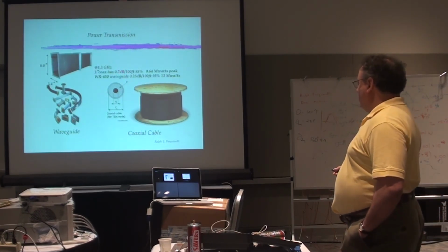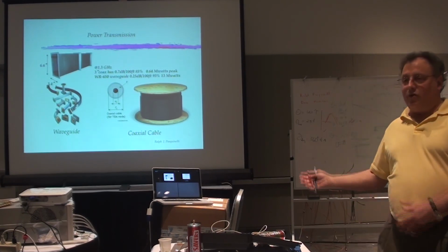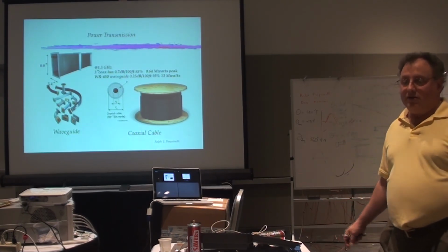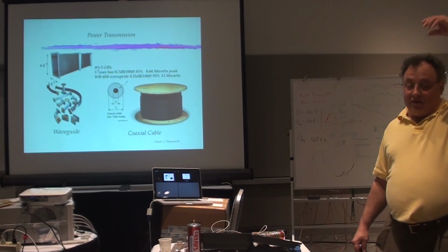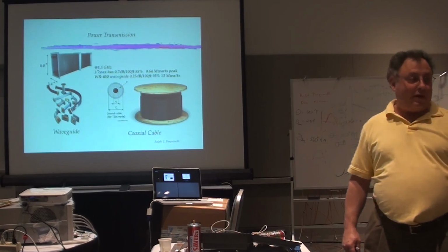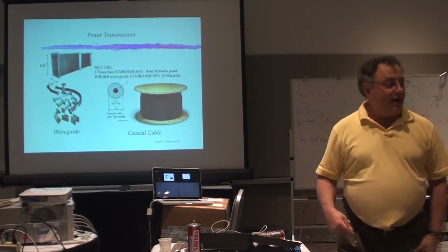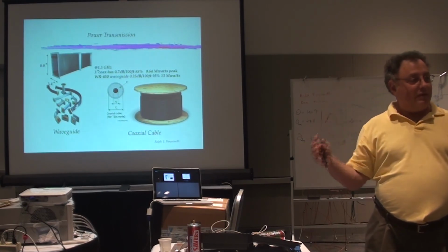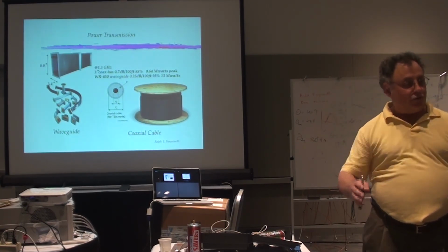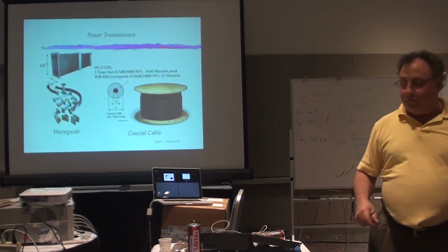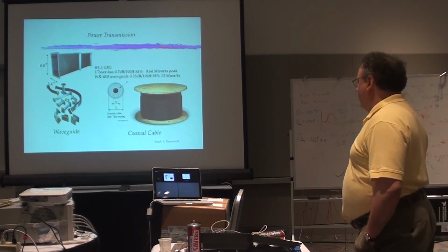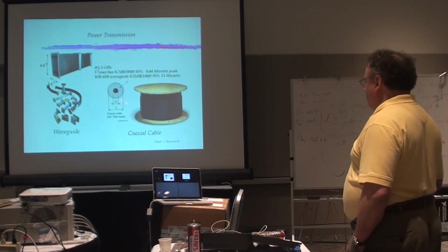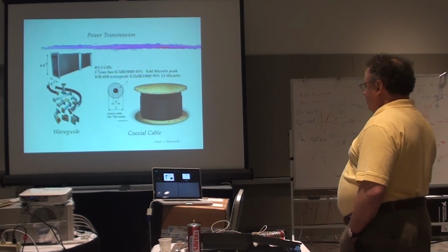Am I going a short distance? Am I going a long distance? Many times you'll see in an installation that you'd like to have the amplifiers upstairs if at all possible, because they are going to break. And it would be nice to fix them up in the gallery by having maybe something you just roll right in, or you fix it in place. Or you have something down in the tunnel where you don't have to worry so much about transmission line losses. This is a decision that you have to make.